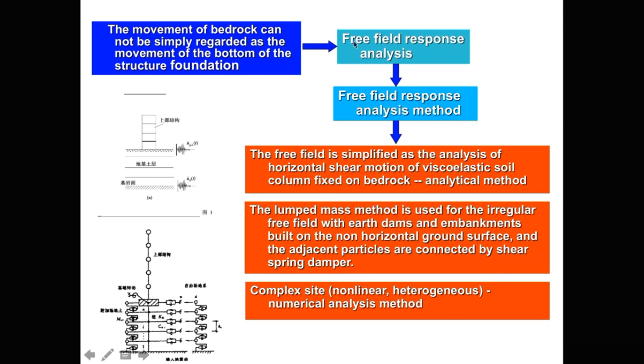And when you want to do this, we have to develop a free field response analysis method. The free field is simplified as the analysis of horizontal shear motion of the viscoelastic soil column fixed on the bedrock. Then we can use the analytical method.